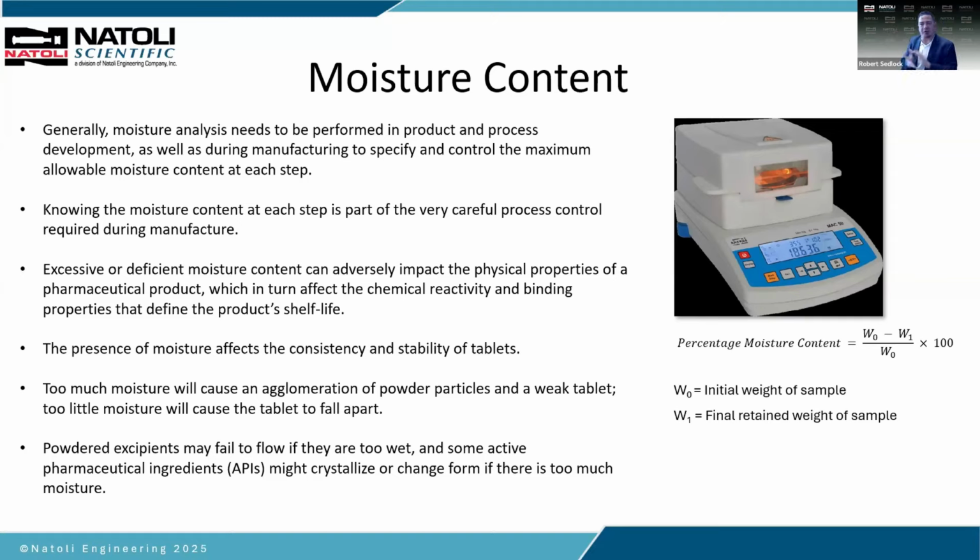But just a general rule of thumb, if you're below 1% moisture, you might have some issues with the particles bonding and compression. You might have some static issues as well with the powder staticky. So we like a little bit of moisture. If you're above 5, 6% moisture, now you might get agglomerations and clumping, and the material won't flow well. You might get some sticking issues, compression issues, and so on. So this is called LOD, loss on drying. There's also something called Karl Fischer, different ways of measuring your moisture.